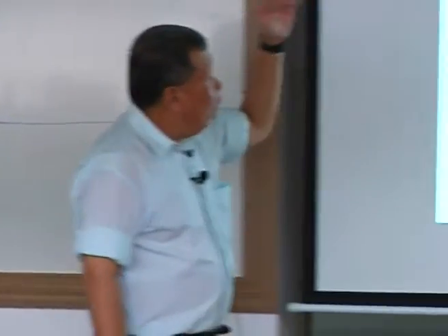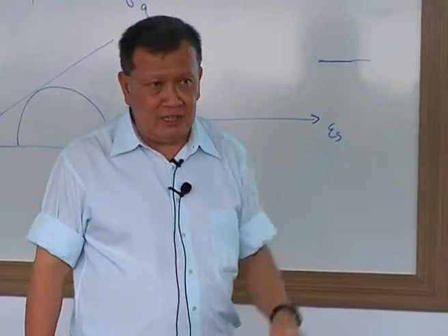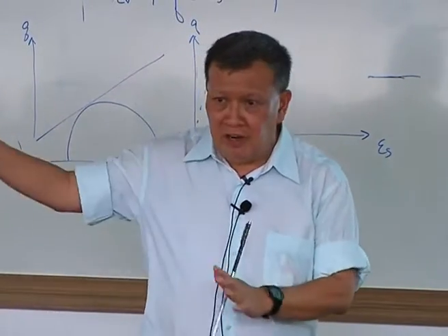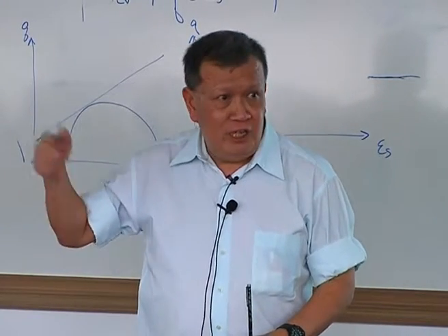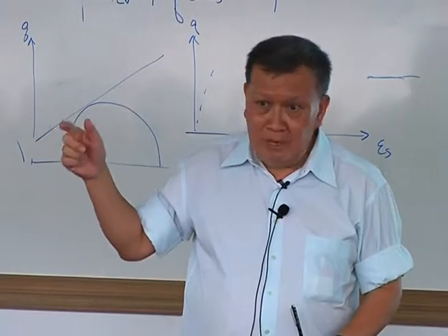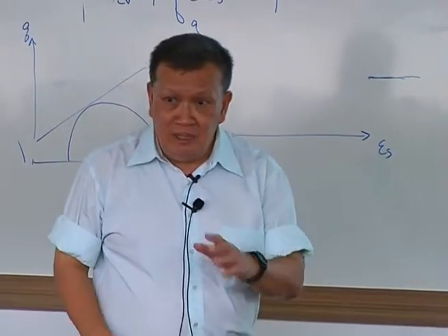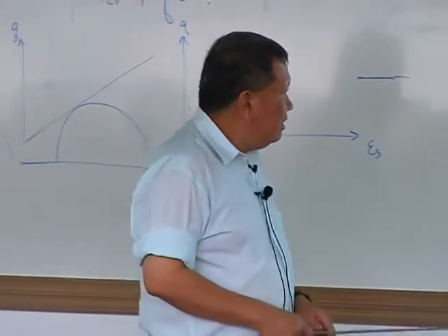So usually I normally advise people to use a linear elastic analysis because, you know why? The people who check the thing will be the structural engineer. So the moment you throw the load onto the structural engineer, he will know how to size the thing based on that bending moment and all that. So he will be able to size it accordingly. And you want him to use the largest bending moment to size. Okay? So this is the thing.